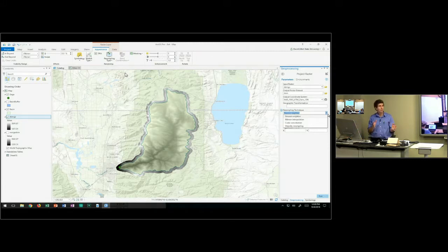So that's some sort of an average of the north-south and the east-west directions. So when you're doing that calculation, you know that you should have got an answer that's close to 8.9. The east-west will be less, the north-south will be more. I'm going to actually just change these to 10 because I want to work with an exact integer meter cell size rather than 8.9 whatever.